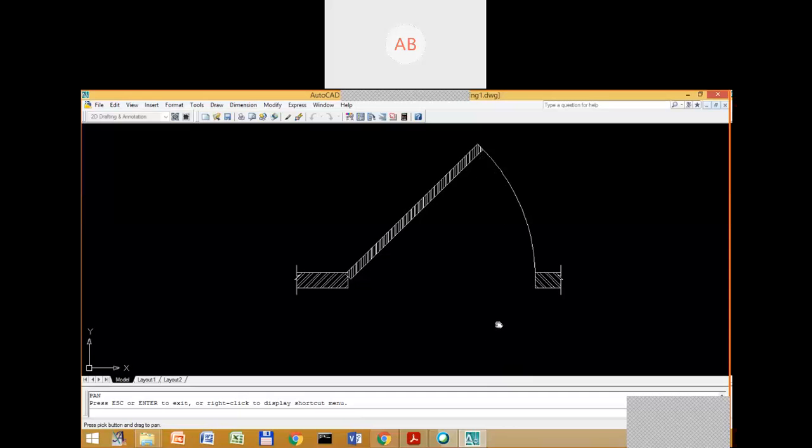Normally in the departmental stores, when you see that one side of the door it is written push and the other side is pull, that is a double swing door. Remember this is single leaf, only one leaf. Sometimes we may have double leaf, single swing. Normally in the old houses, we have this kind of door. Again, we can have double leaf, double swing door.